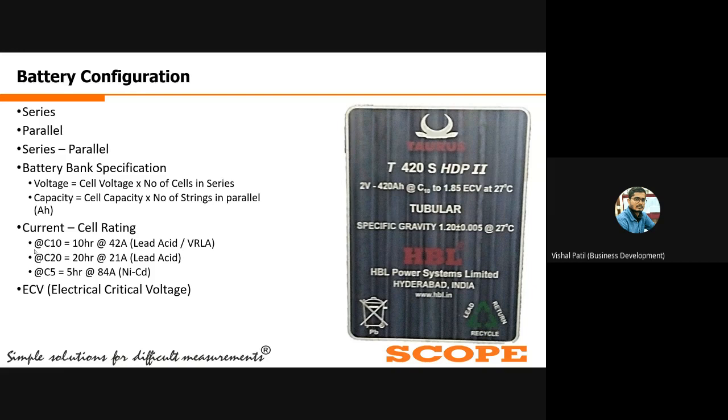Also, for a few special applications, battery manufacturers make cells with an electrical critical voltage of 80 or 75% of the nominal voltage. So you always have to check this ECV mentioned on the cell, and whenever you are using these cells or battery banks, you have to maintain this electrical critical voltage.